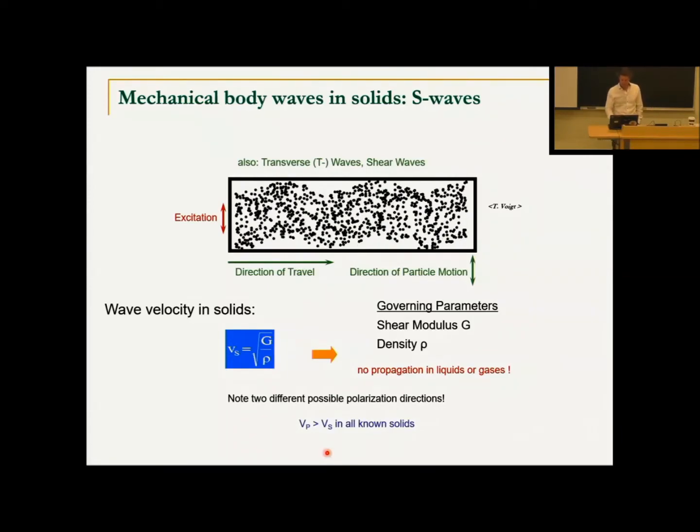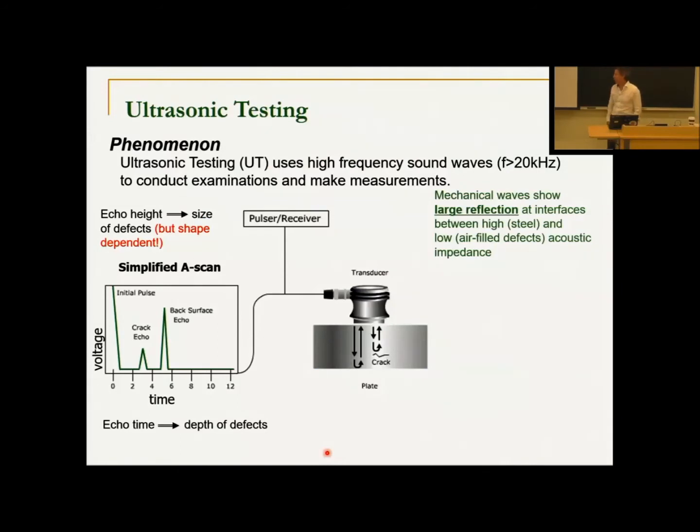Okay? Now that we have that basic understanding of waves, how can we use this wave propagation in a non-destructive testing tool? Well, ultrasonic testing, or UT, uses these mechanical waves, directed in a certain direction, and normally with a fairly high frequency, meaning, and we already know this for a constant velocity, that means a small wavelength, and I will indicate the importance of wavelength.